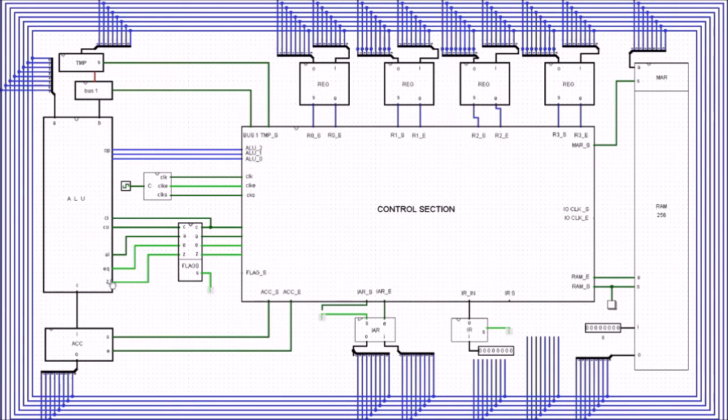So we need to take a little snapshot of these values whenever we go through this ALU instruction, and we do that here with this register. All we do is store these bits of information in 4 bits in this register, and we set the information in that register from some point here.